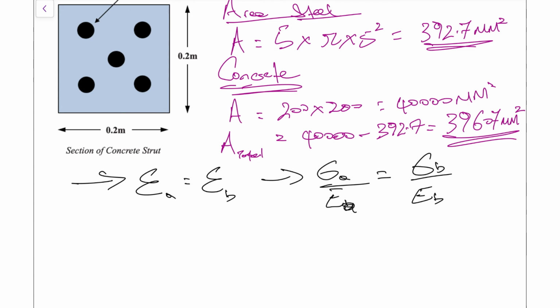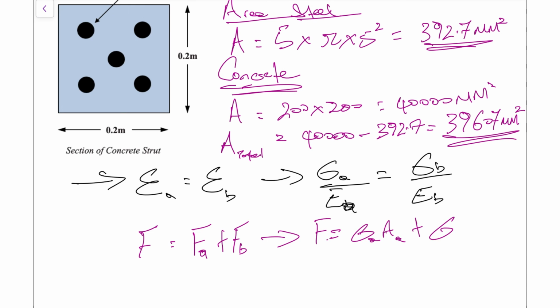Now the next thing that we need to also notice is that when that external force acts, it will be distributed across the material. So we'll have some of that force distributed across material A, but when we sum the force across A and B, that should give us the same net result. And for the forces, we can substitute our forces with our stress times area formula. So for this one, force can be substituted using stress times area for A, and for B, stress times area.